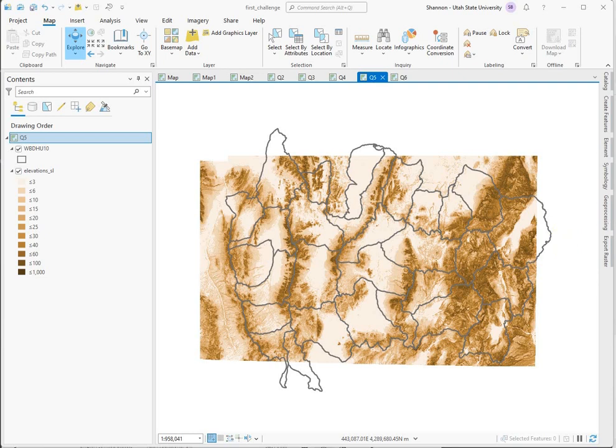All right, for question 5, we've moved into a different set of data. We're in part 2 data, and this question calls for the HUC10 polygon shapefile and the slope layer that was calculated from the data set called elevations. The question is to find the name of the watershed that has the type closed with the lowest median slope.